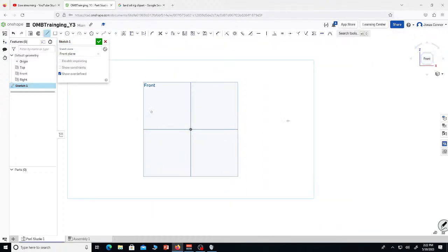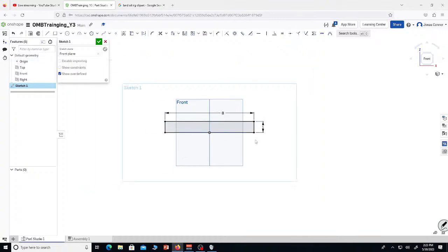So we'll just say like a line here. It's like one inch, 8 inches. Now typically you want to have your part defined off the center, but we're not going to do that because we're rebels. What we'll instead do is just have a square. We're going to make this perpendicular. And then we're going to make the center of this, or the midpoint, coincide, and where's midpoint? Midpoint. Boom, boom. Okay, now it's kind of attached.